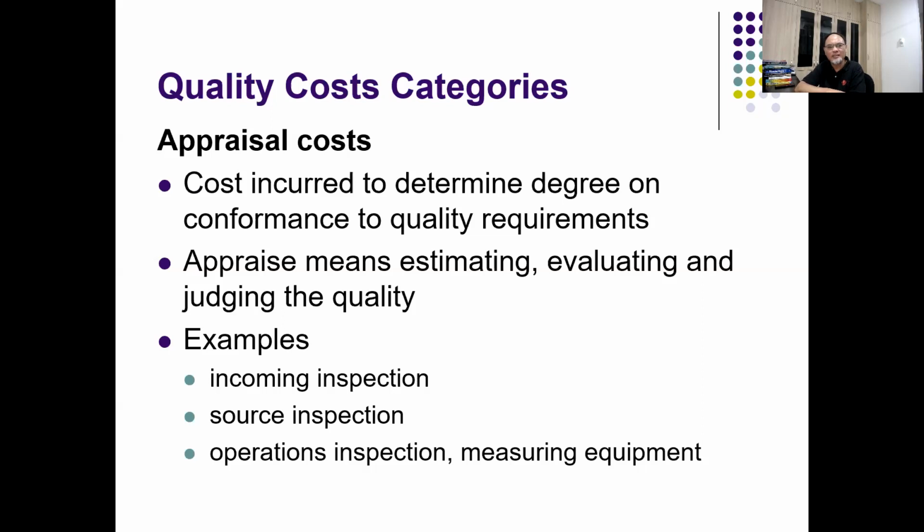Appraising, just doing it, is not value adding. Inspection is not value adding. It's just confirmation. But of course, you need to do incoming inspection because you want to do some sampling. There are standards in manufacturing, military standard MIL 105E, for example, used for incoming inspection sampling. You don't have to do 100% inspection or source inspection at the facilities.